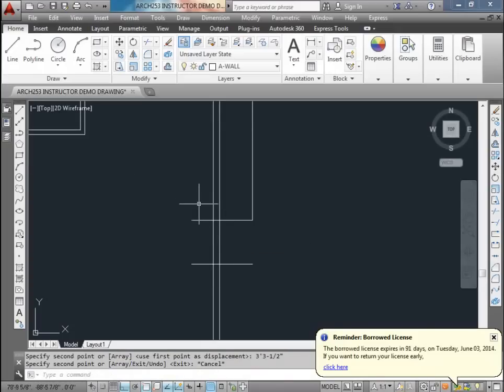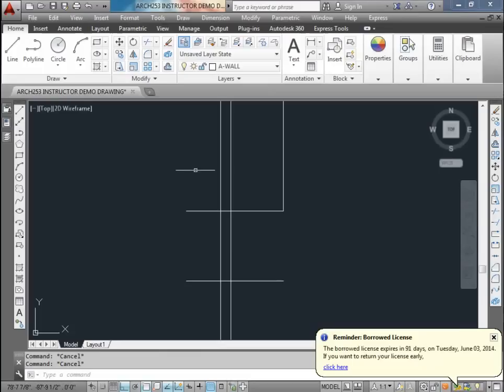And I'm also going to draw another line. It's going to be from, I will say, from this point here. And we need to draw it in, I think we said, actually, just real quick here, I think we said that we need to have at least 3 inches. So let me just do 2 inches here. That's going to be the point of the foundation wall. And then we want to be at least, say, 4 inches in. That's going to be the inside of the chase there.